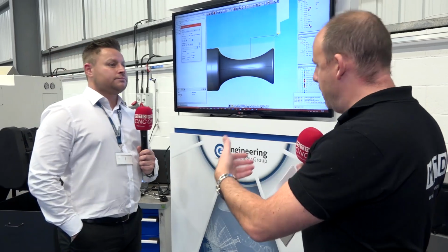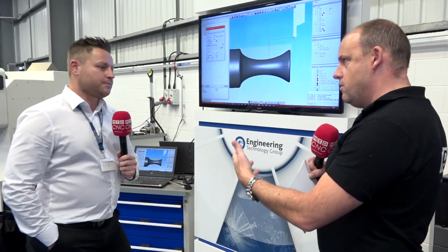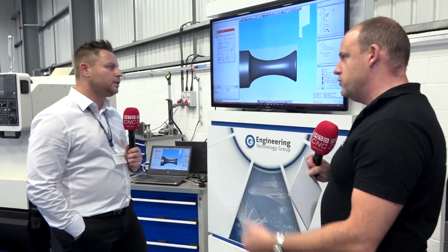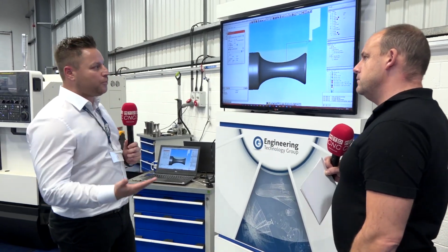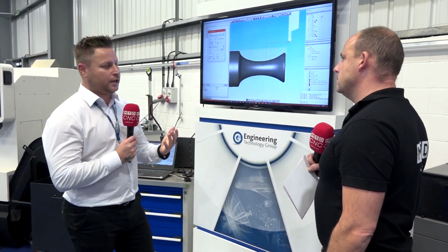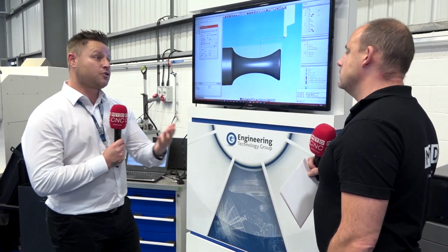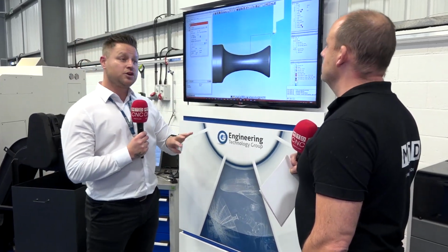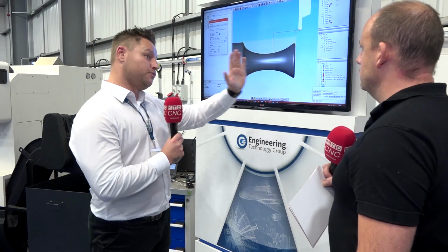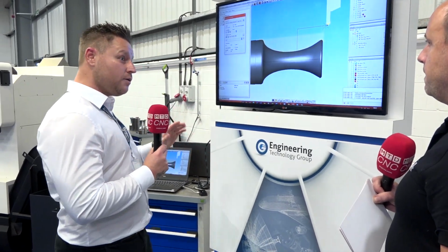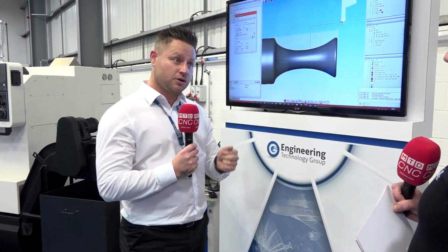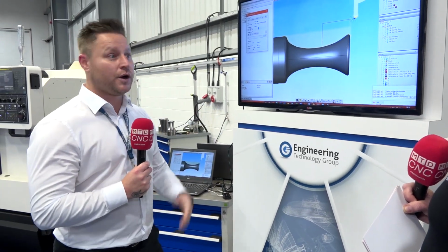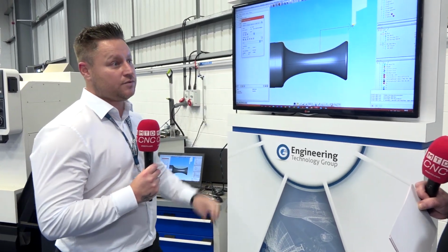Are there any negatives to this strategy? We have to look pragmatically. Yeah, 100%. Are there any areas people just have to think about? For example, if you use a tool with a screwed insert, where you screw it down, you can't use ramping. When it machines towards the chuck, the insert tightens. When you machine with ramping, it will machine forward and reverse. So now the insert loosens, the screw loosens up, and you might blow your tool when you use ramping with a screwed insert.